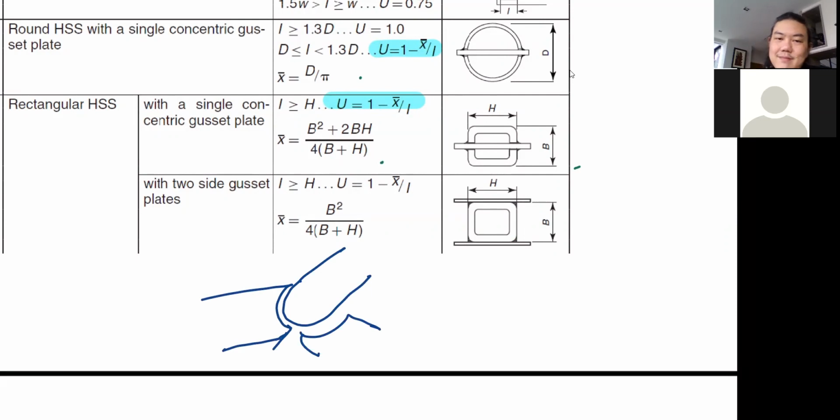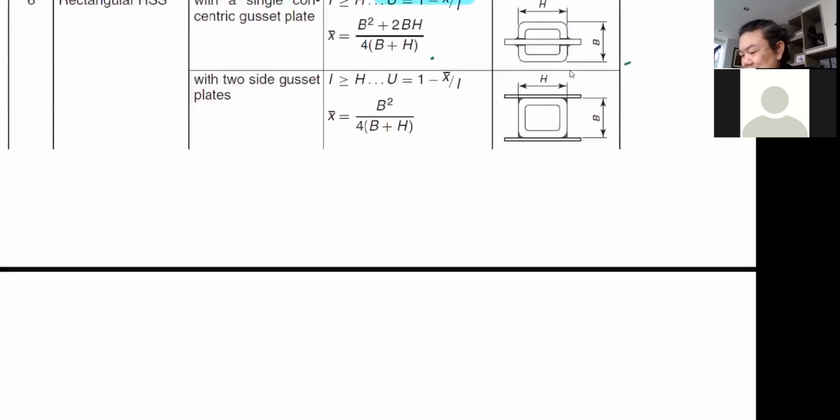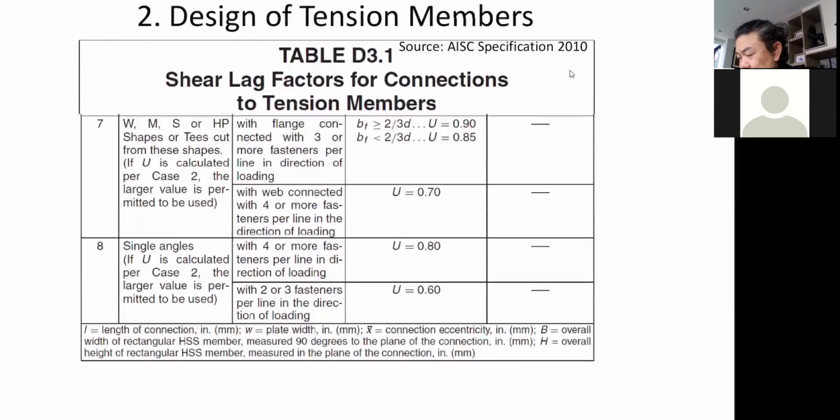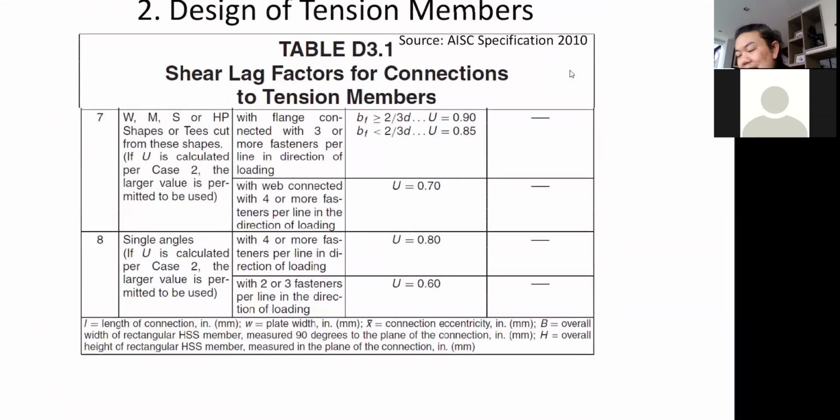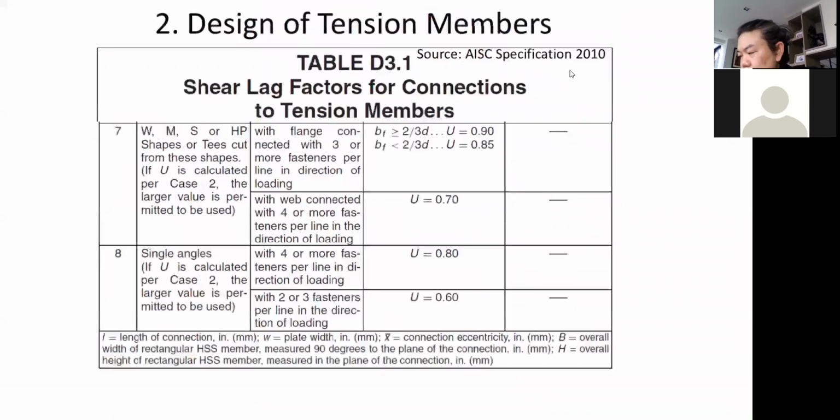And if you can weld them through like that, I don't think you have to be concerned with the shear lag problem. It's an ugly picture. I'm just going to erase it. Anyway, more on this. If you are lazy and you don't want to calculate shear lag, they also have numbers you can use based on these conditions. But in general the formula itself is not so difficult.